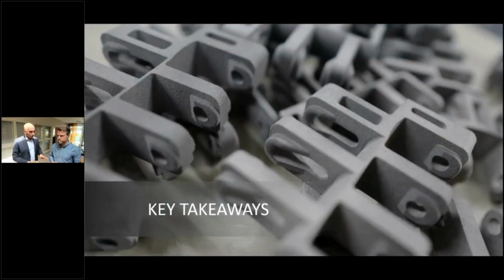That was it, the 3 main areas. I skipped the spare parts. I think that's coming more and more, so I don't have any really good examples of that right now. What you've seen is that additive manufacturing can be used in prototyping and design, tooling, and production in many areas. This is just a few, the most common ones we see. And if you don't use it already, especially for rapid prototyping or fixtures and jigs, just do it.